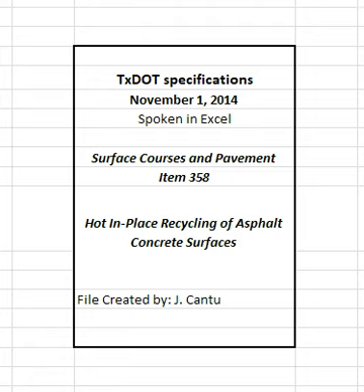Use a permanent marker or paint pen to record the date and lot number on each core as well as the designation as core A or B. The engineer may require additional information to be marked on the core and may choose to sign or initial the core. The engineer will take custody of the cores immediately after they are trimmed and will retain custody of the cores until the department's testing is completed.